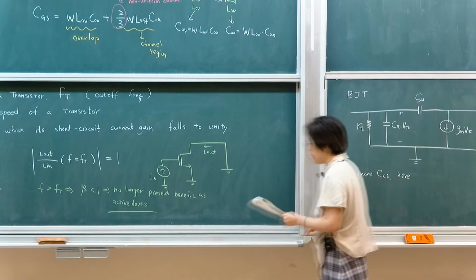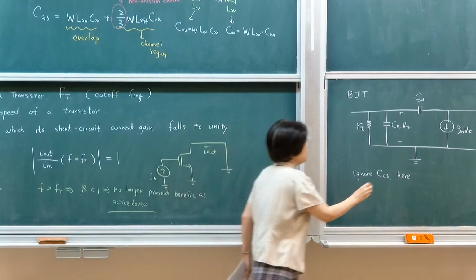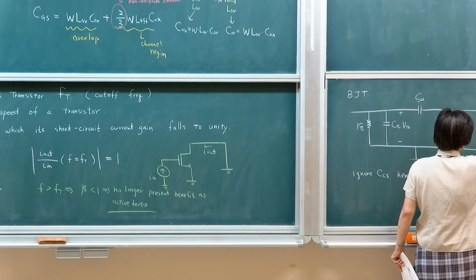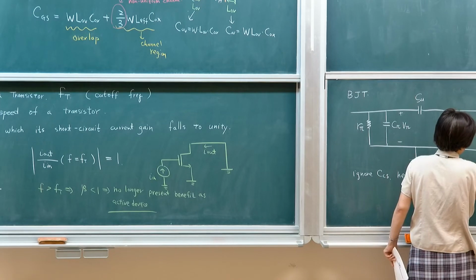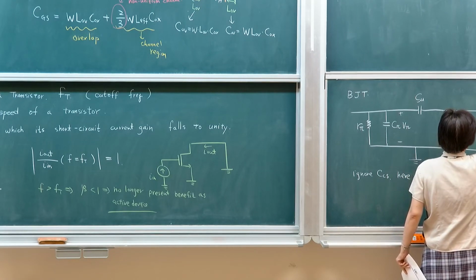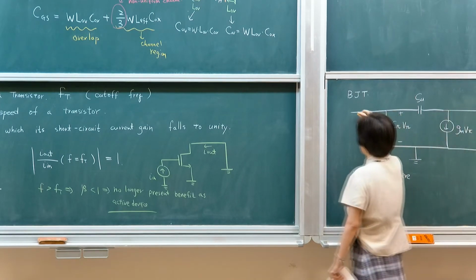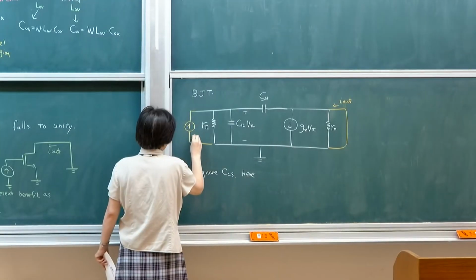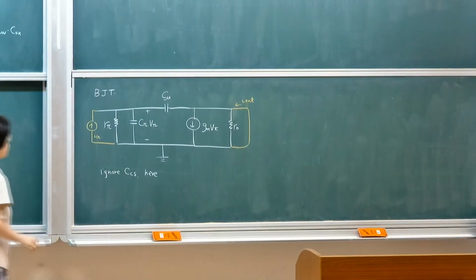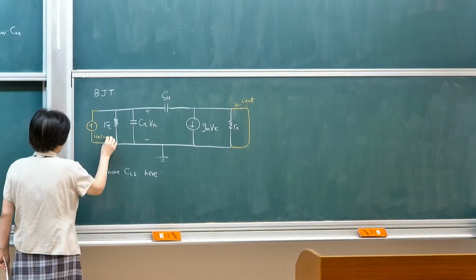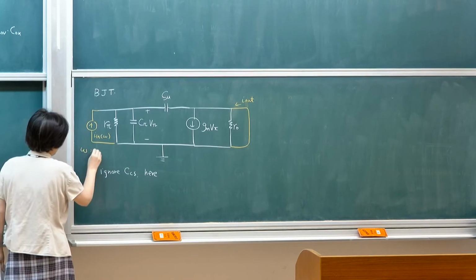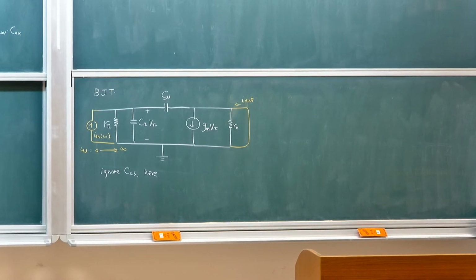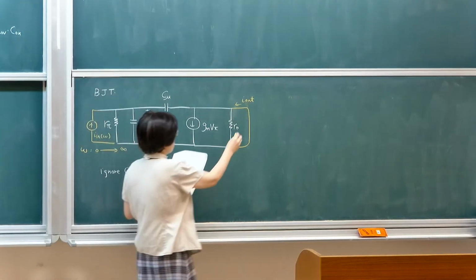So external circuit is like this. The testing condition is that I short the output. This will be RO. So the circuit is that it's shorted. And then we're going to look for this I out in response to an input sweep of frequency. So you simply generate input as you sweep frequency from 0 to high frequency, and then look for the output response in frequency.